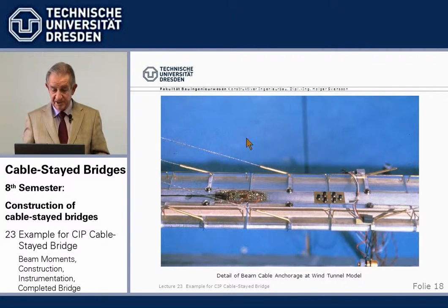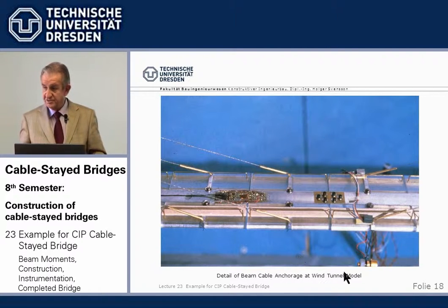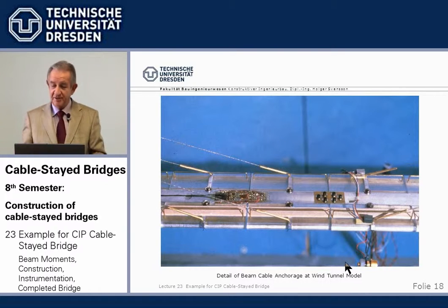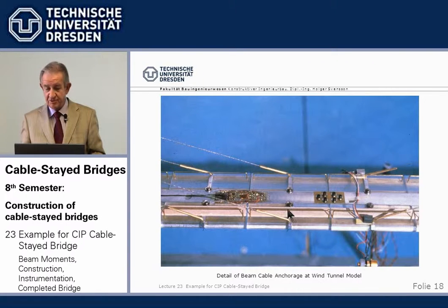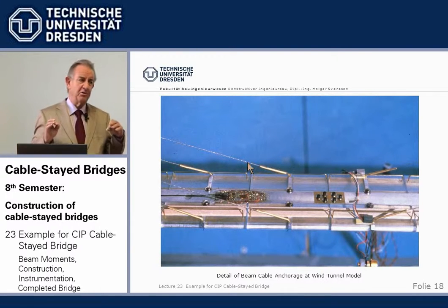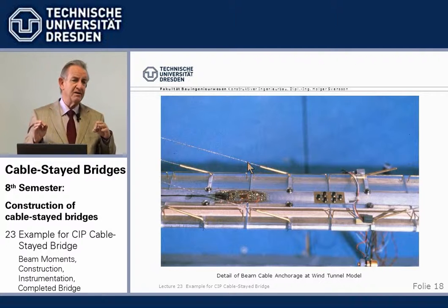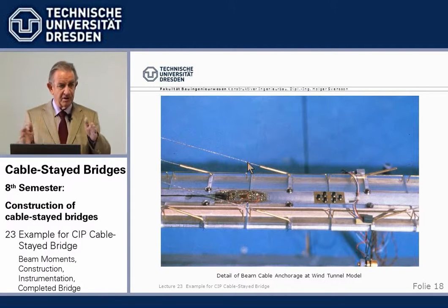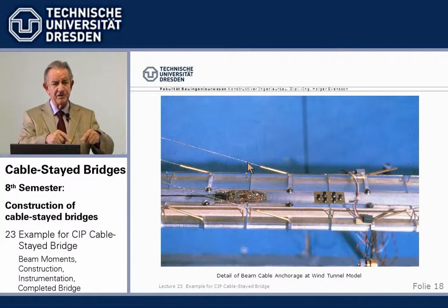Very nicely detailed. This shows a detail of this wide as a hand beam in there with all, these are the instrumentation to measure all the things, and the cables are nicely simulated. You can do that only very limited. We say use a section model to get the characteristics, a pattern model, 1 in 20 or so. There you can detail, and then you use the results from there in a computer calculation, as we did. The scale does not permit to really show the details.